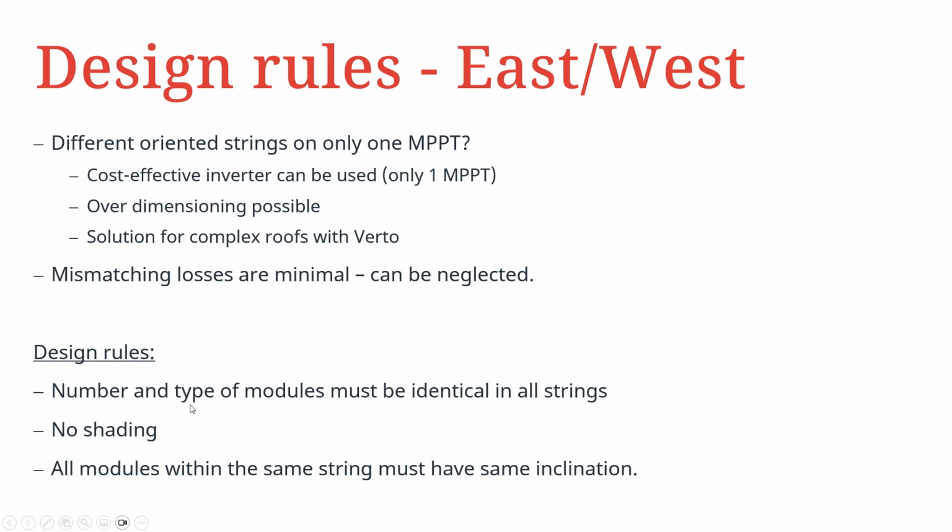The number and type of modules implemented for such systems must be identical in all strings. Please ensure that as much as possible there is no shading, and also ensure that all the modules within the same string have the same angle of inclination.